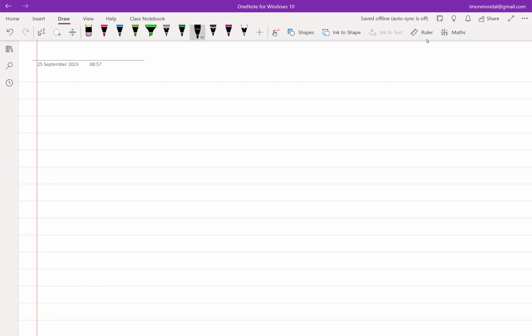This is one simplistic example of an audio amplifier, but you can extend the analogy to any electronic system. Whenever you're making any electronic system, you'll have to ensure that the transfer function of the system is reliable. By reliable, I mean it doesn't really change with the whims of the weather. Clearly, a common source amplifier doesn't fall into that category. If you use a common source amplifier the way that we have been doing till now, your gain will be dependent not only on the load but also on the ambient conditions. So this is not good. We need to address how we can fix this.